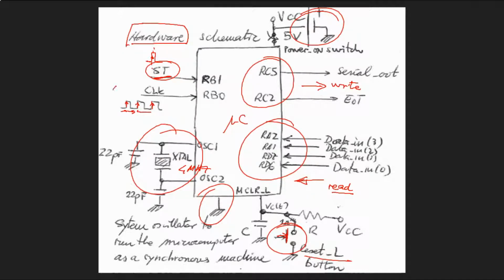So the clock and the start button are special because they are edge signals. They are edge sensitive. You want to detect exactly the active edge. You can program that. It may be the rising or the falling edge, but you have this idea in mind, detecting the edge.